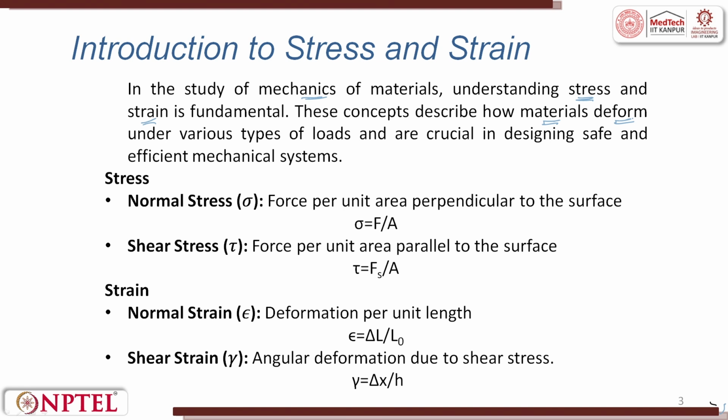The loads can be tensile, compressive, bending, shear, torsion or a combination, which are very crucial in designing safe and efficient mechanical systems. The stress is always defined as force per unit area.